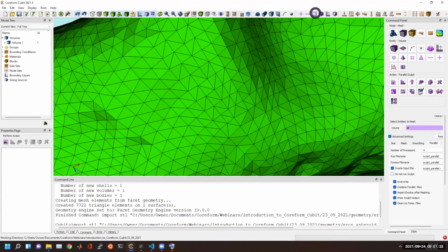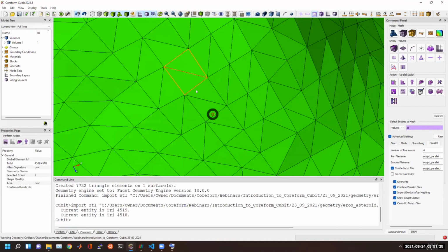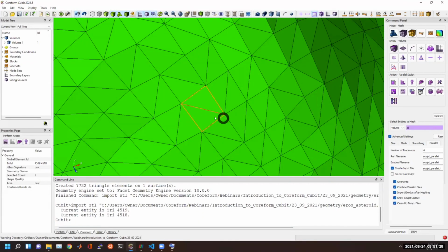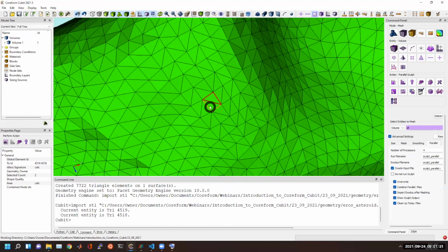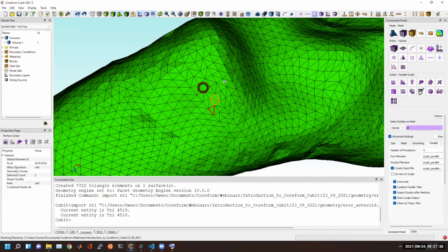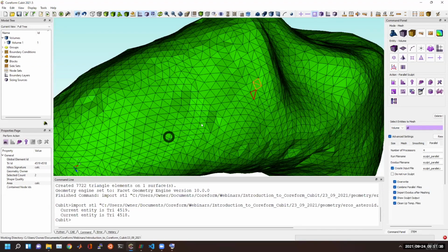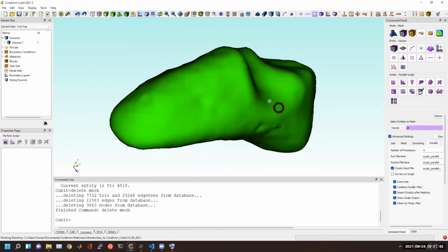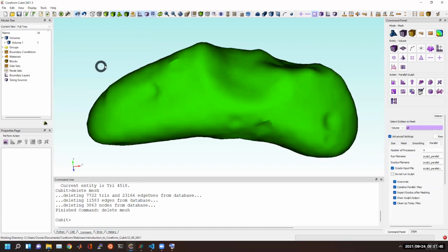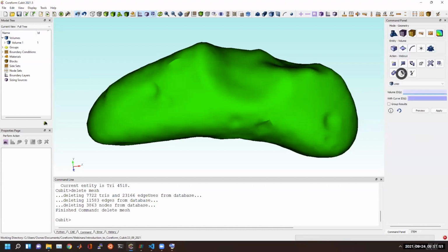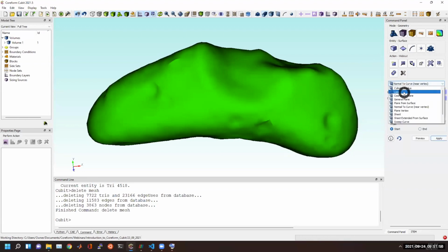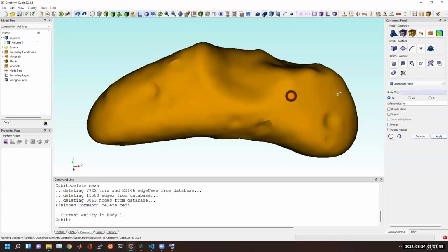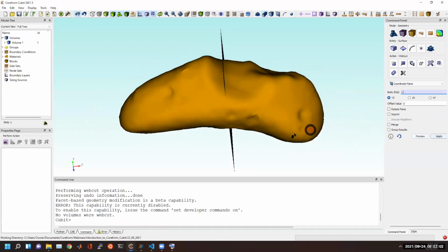So what's being asked here is you can see how these are two triangles that can be joined across the split edge. And so there are some facet modelers that will identify those and join those together. But what we can do in Cubit is just remesh with quads. Now the quad mesher does require a split. It has to have at least one curve. So what we can actually do here is cut this surface, say by a coordinate plane. So we just cut it in half here.